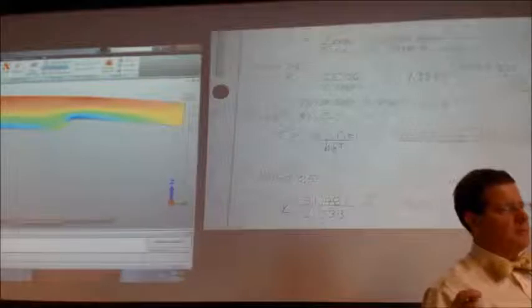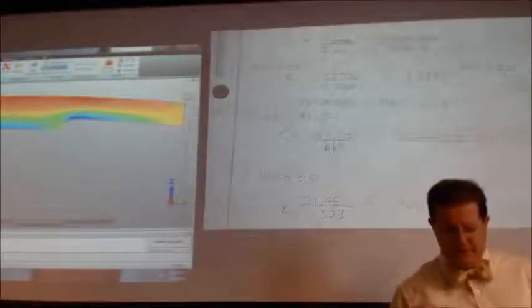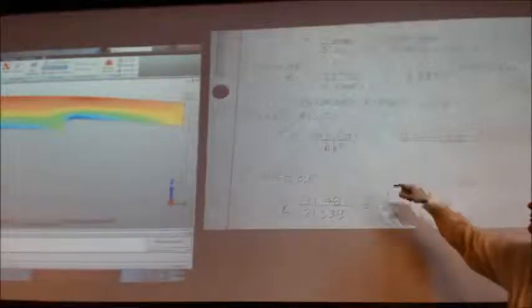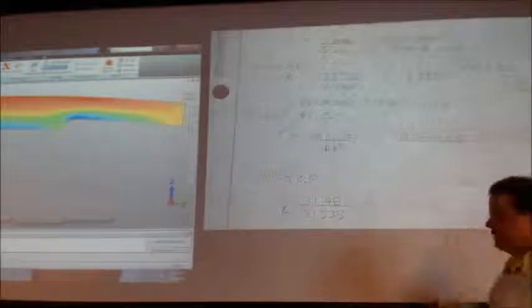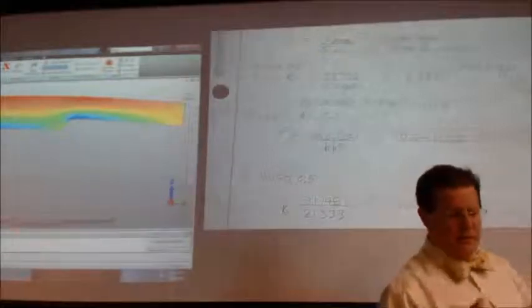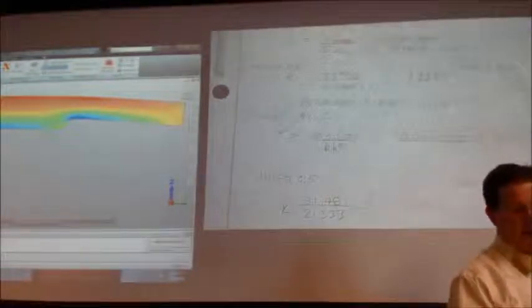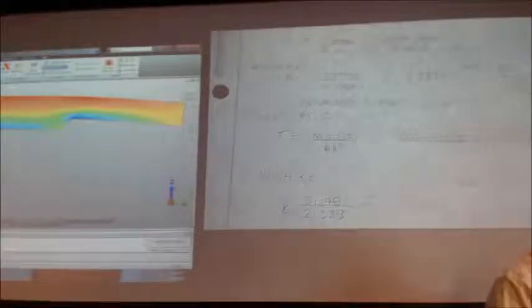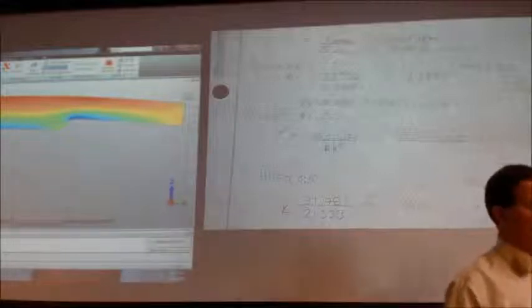I have now ordered my own copy so that I can look these up. But in any case, we can do the numbers and continue to refine the mesh until we get close to the reported value. I didn't do a lot of refining on this one. I refined a different one. Well, we'll get to that. Anyway, that's how you go about doing that.